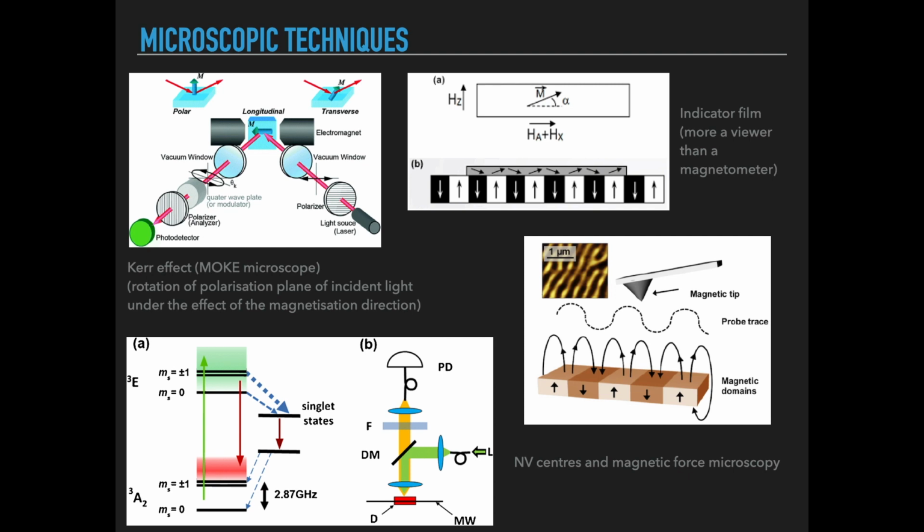Another similar technique, meaning that it is a scanning technique, instead of using a magnetically coated tip, uses nanodiamonds with a particular microstructure where a nitrogen vacancy generates an optical transition that is sensitive to the magnetic field. Again, the nitrogen vacancy is placed in close proximity of the surface of the sample, and the fringing fields generated by its magnetization are capable of affecting the optical transition. If that transition is measured, again, you have a means of imaging the magnetic configuration of the surface of the sample.